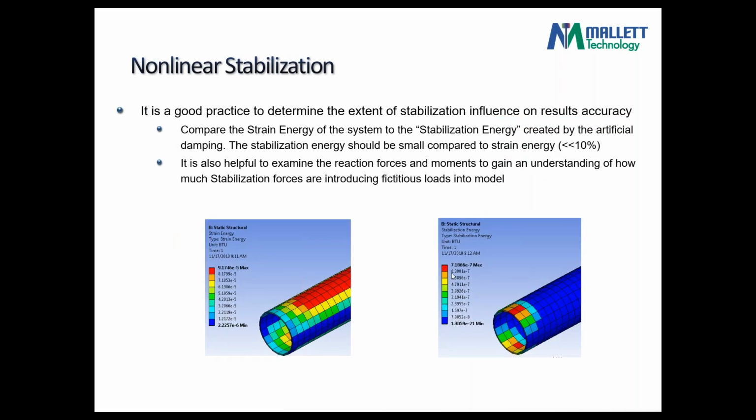Another way to measure quality is to check energy. We're talking about stabilization energy being applied by these dampers. The program will give it to you as part of the post processor. Make sure that energy is less than 5 to 10% of the overall energy.